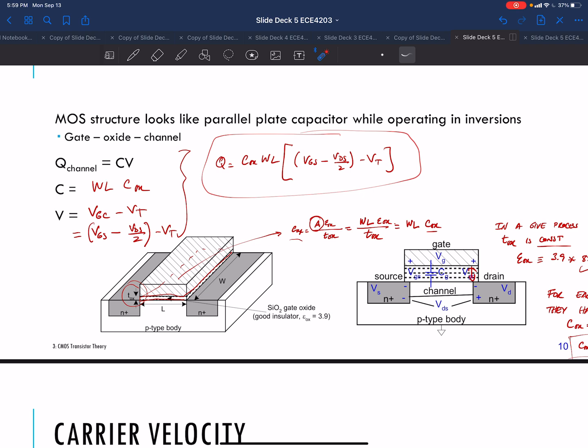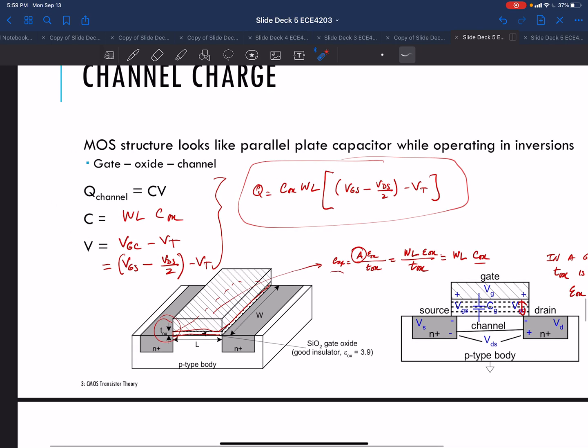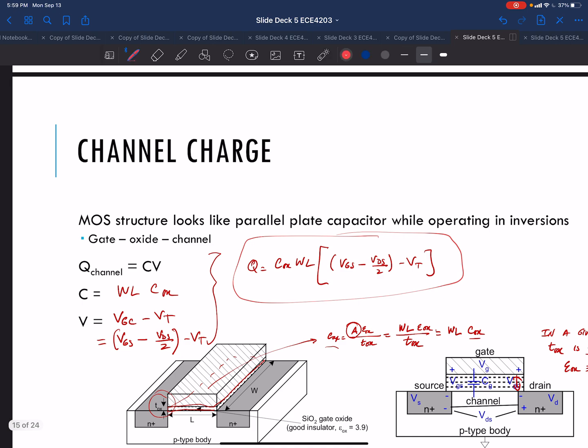We're approximating that as just the average voltage minus the threshold voltage, which is a pretty big approximation, as you'll see. Because there's all sorts of electric fields here, and it's not quite a clean geometrical picture as we've drawn here. But anyway, just remember that this is really a level 1 model.